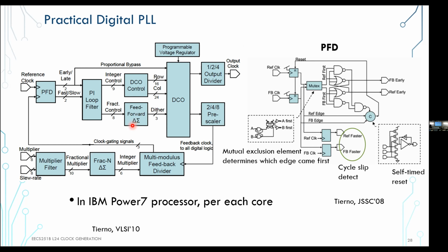So one thing is that the feed forward path, or basically the proportional path, remember, because this one is kind of bang bang, right? It applies a little delta sigma here to try to dither that, let's say plus minus early or late, to try to establish a little bit more precision in where it needs to go, right?